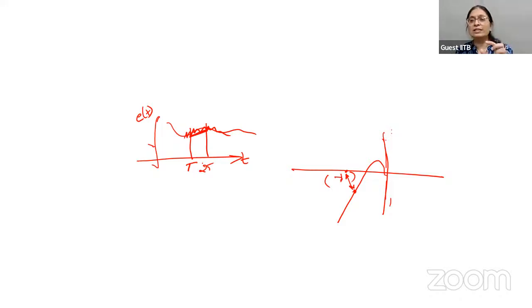So what is the stability margin helping? This will allow my proportional gains to be this much, right? Not exactly this magnitude, which we can always map it to. So my proportional gains can become this much. Now, with the derivative control in the loop, we are adding phase lead.